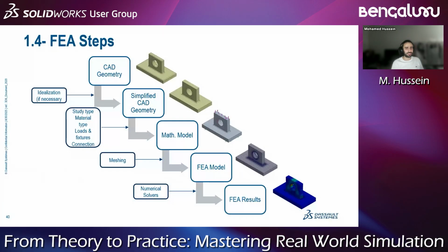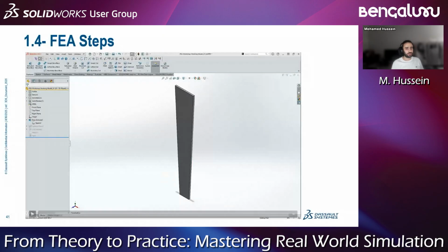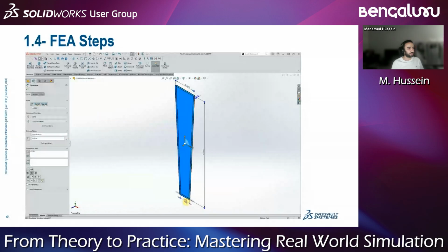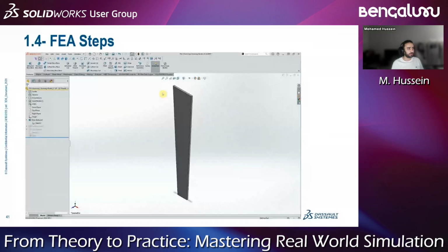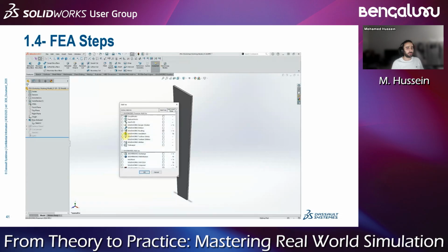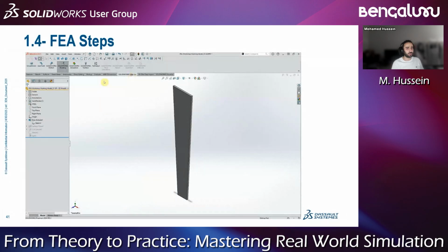Again, I will use the same 5 steps for my finite element. So here is the first. What I'm doing right now is that I have modeled my model in FEA. This is W2, W1, 2 inch, 1 inch. The length is 10 inch, and I have a thickness of 0.125. Okay. I can go to options, add-ins, and I can activate the SolidWorks simulation, or from that tab for the add-ins, I can activate SolidWorks simulation.